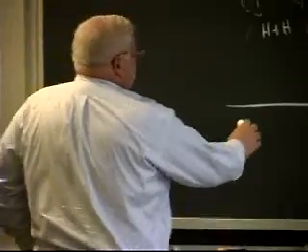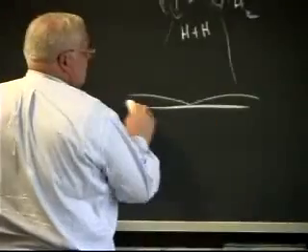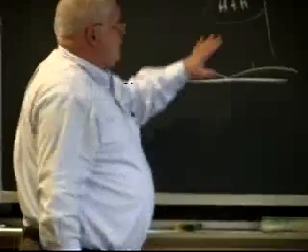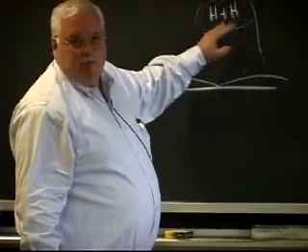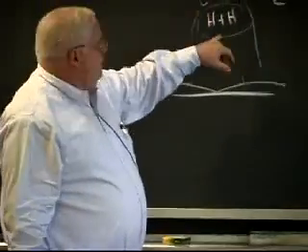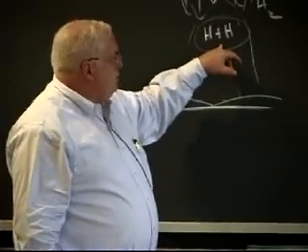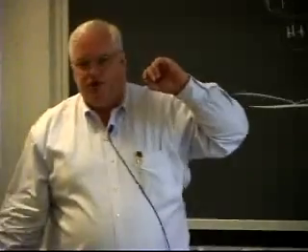Down here in the thermal boundary layer, first of all, this is dissociated because of the high temperatures. Above about 5,000 Kelvin, diatomic hydrogen splits into monatomic hydrogen, and there's a heat of dissociation. Okay? It takes energy to break the bond. And I have to get to 5,000 degrees, so it's a fair amount of energy to break that bond.